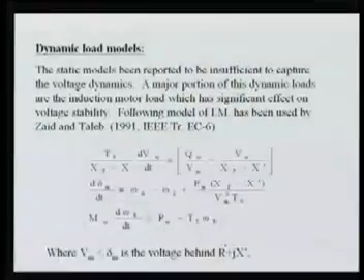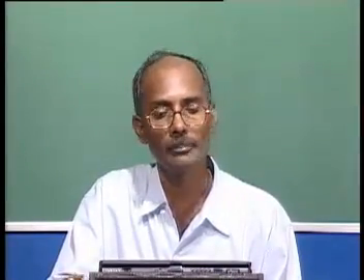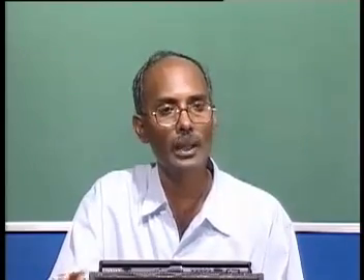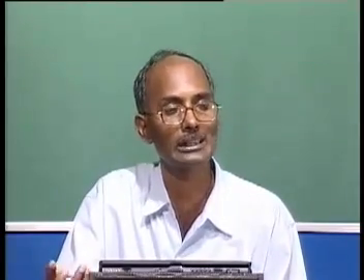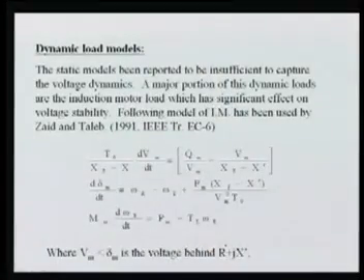The main purpose of transient stability or any program is that we can reproduce and know the exact behavior of the system by simulating. In the simulation we have to ignore assumptions as much as possible. So to include this voltage dynamics, we should include the dynamics of the load as well. A major portion of these dynamic loads are the induction motor loads.